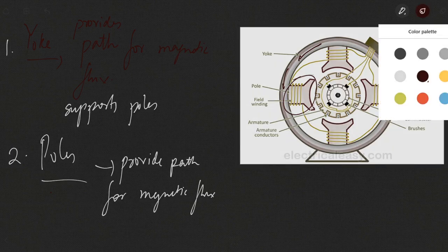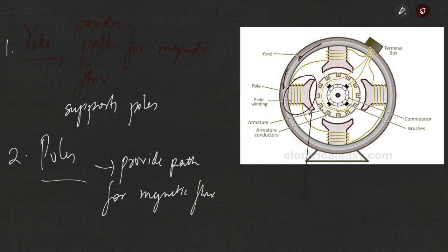Fine. So this part here is known as pole shoes, and this part on which the windings are actually wound is known as the pole faces. So pole faces basically allow the windings to be wound, and these windings are actually the field windings. The field windings will be connected to an external DC voltage source, so that current is established through these field windings,